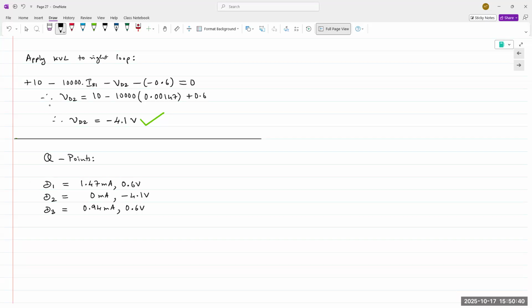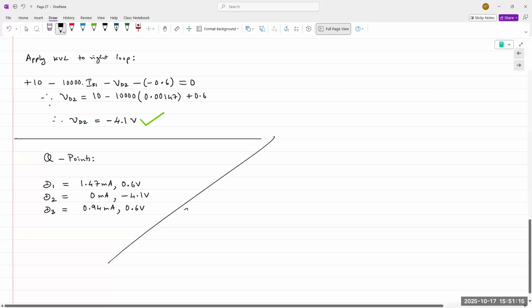Well, what do you mean by results? So the question being asked is, would we obtain the same overall result? The answer is yes. And as you pointed out, the numbers would be different because instead of 0.6, it's 0 volts. But the overall result, meaning diode D1 is on, D2 is off, and D3 is on, we would still obtain that same overall result, which I usually point out that students should try at least 2 different assumptions.